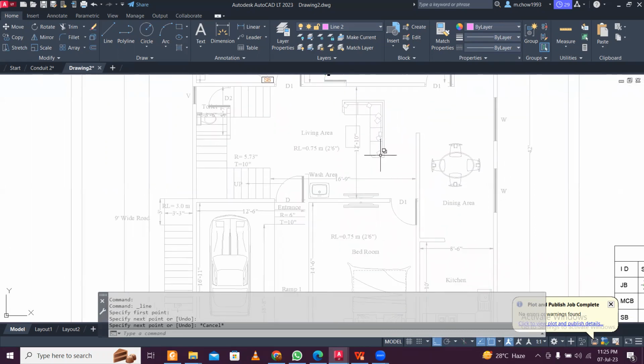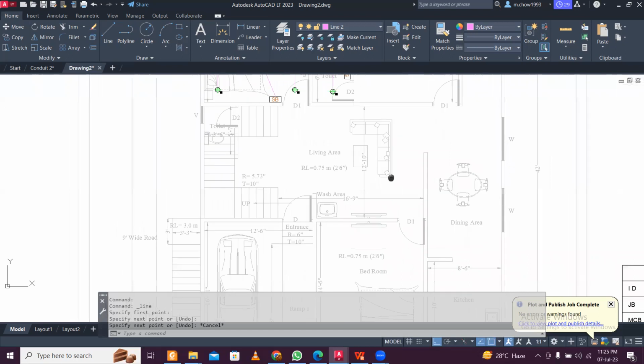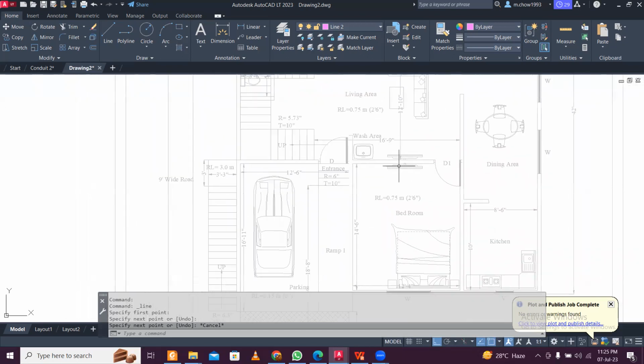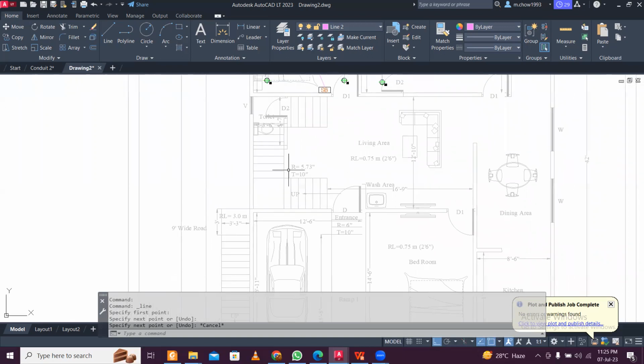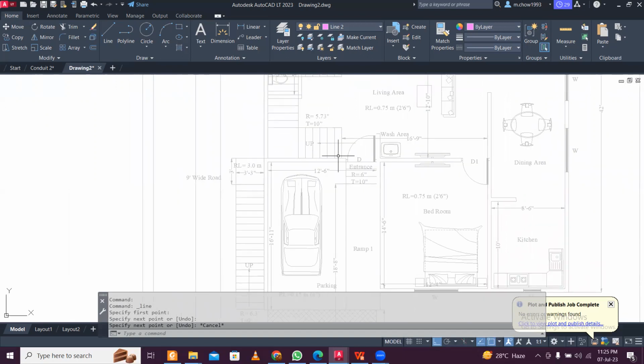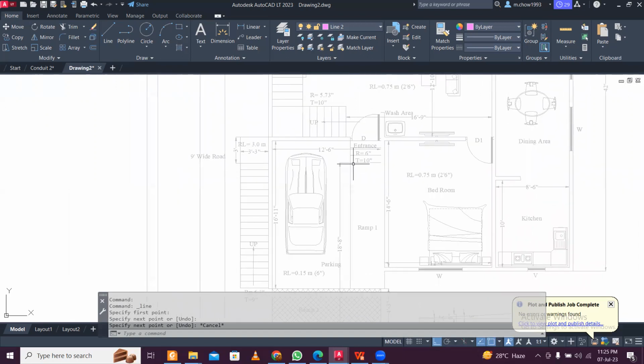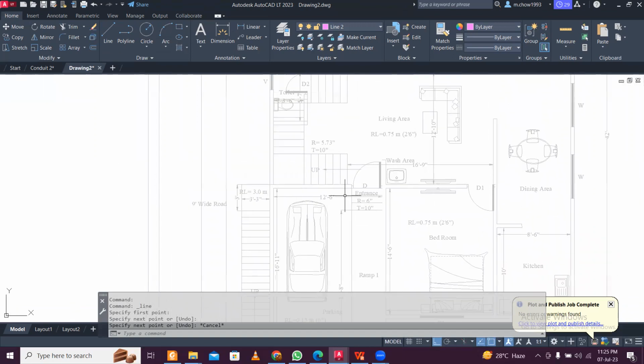But another important thing which I want to show you is the MCB location. So MCB location can be near the stairs or below the stairs, some location where it's beyond the reach of children. It is best if you give it in such a location, and also where adults can access it anytime, where if you want to turn it off, you can turn it off easily.